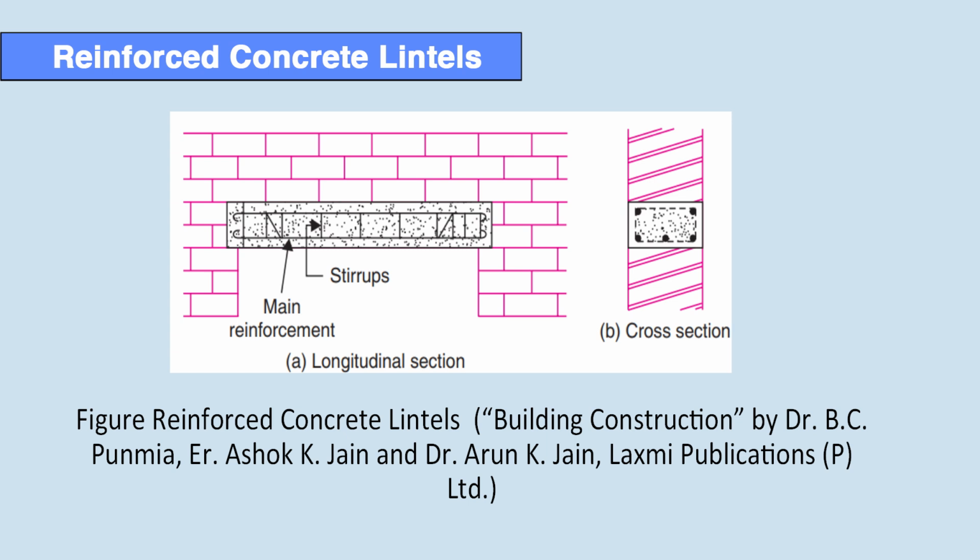Reinforced concrete lintels are available as precast units, though cast in situ units are more common, requiring formwork for construction. For cavity walls, reinforced concrete boot lintels may be used, offering a better appearance and reducing the amount of concrete required. However, the toe section of the boot lintel must be strong enough to bear the load. A flexible damp proof course, known as DPC, is provided above the lintel to prevent the seepage of water.